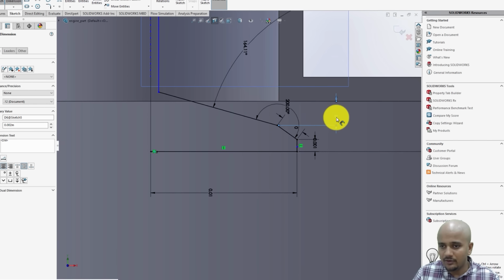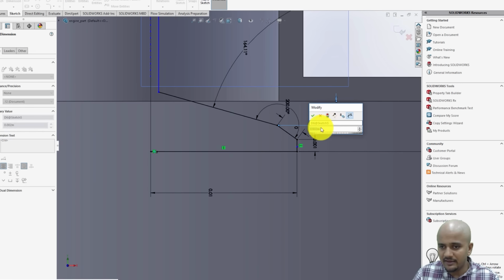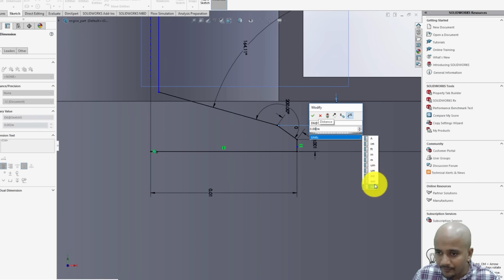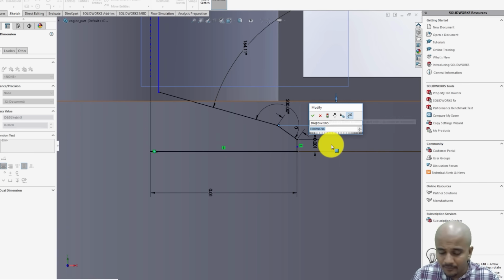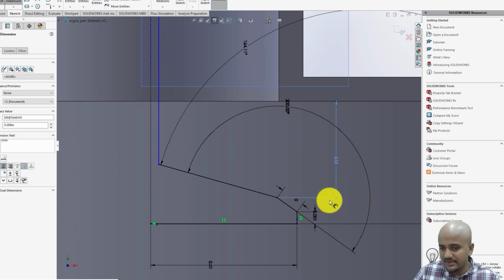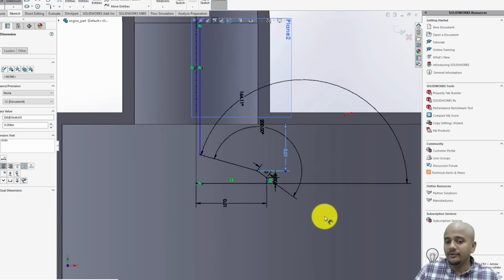Okay, and what I can also do is I can just select that guy. If I want to increase it to 8 mm, I can just type in 0.008, and if I hit OK, there we go. Now you can see that it's pushed open by 8 mm. So this is what you need to do to vary your valve lift consistently.